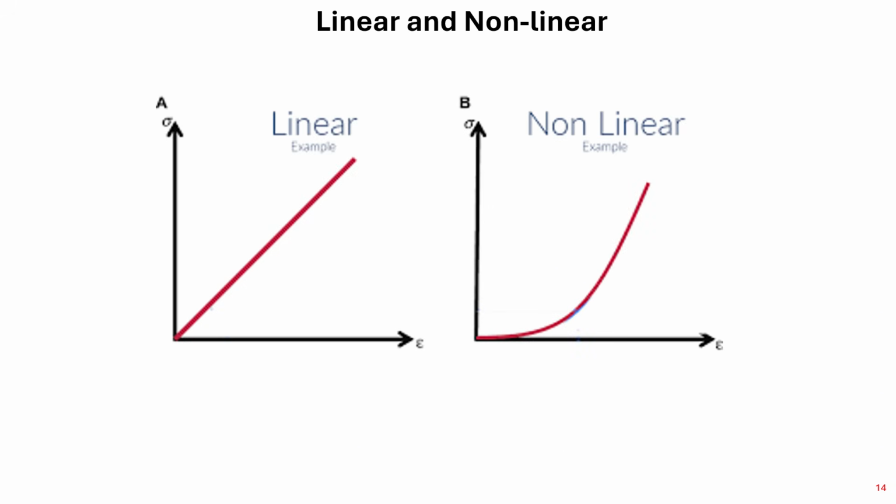So linear means, actually this is an example, that is the ramp function, y(t) = t x(t). So this is linear, and if it is a square now, particularly like x squared, in that case your system will be non-linear, right? y(t) = 5x(t) is linear, and y(t) = x(t) whole squared is non-linear, because in this case the superposition principle will not be valid.